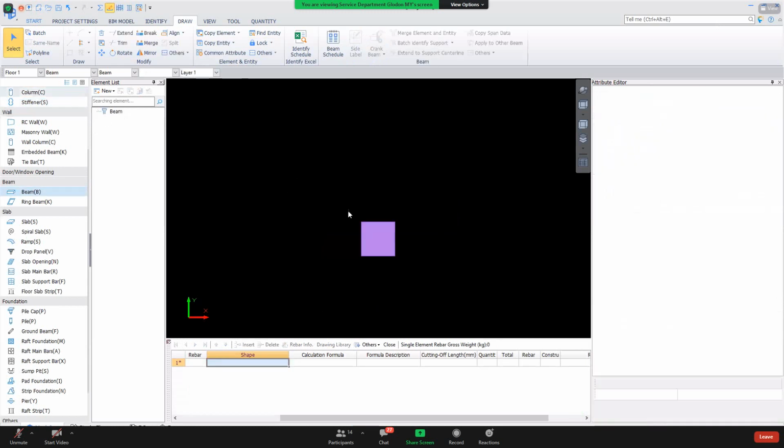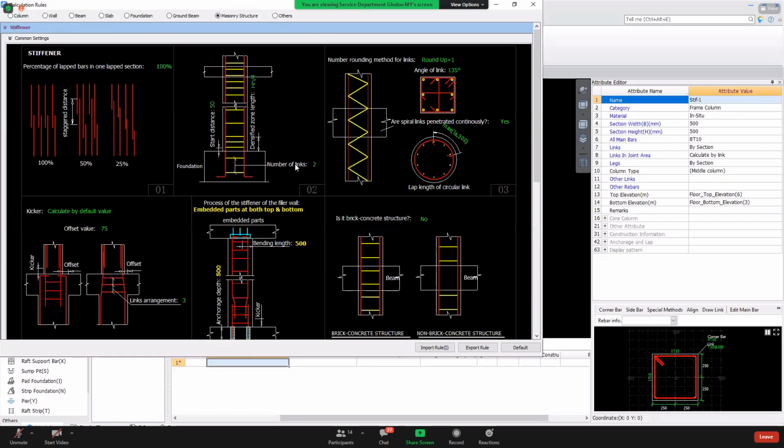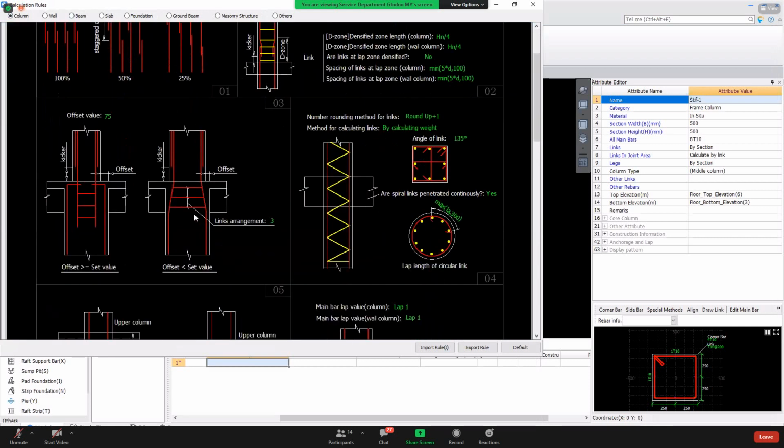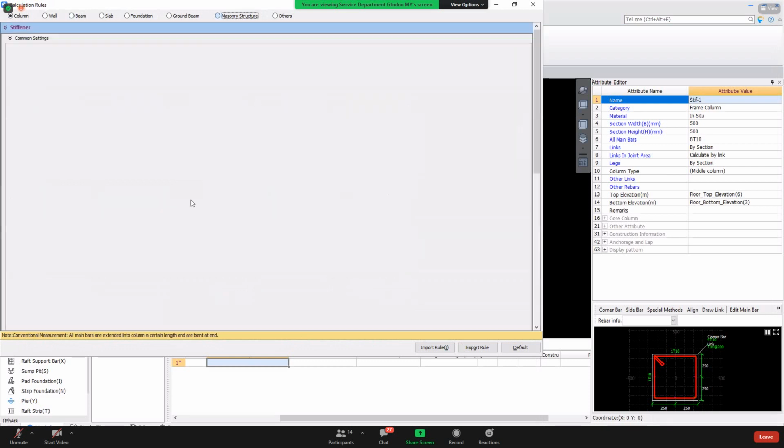Then it will also act the same. But for the settings, you can use column settings. For example, like calculation rules here, you just go to column settings. Whatever you do for those stiffeners that I converted to column just now can be adjusted inside here as well. The concept I was mentioning just now was that these few items are supposed to follow this for the masonry structure.